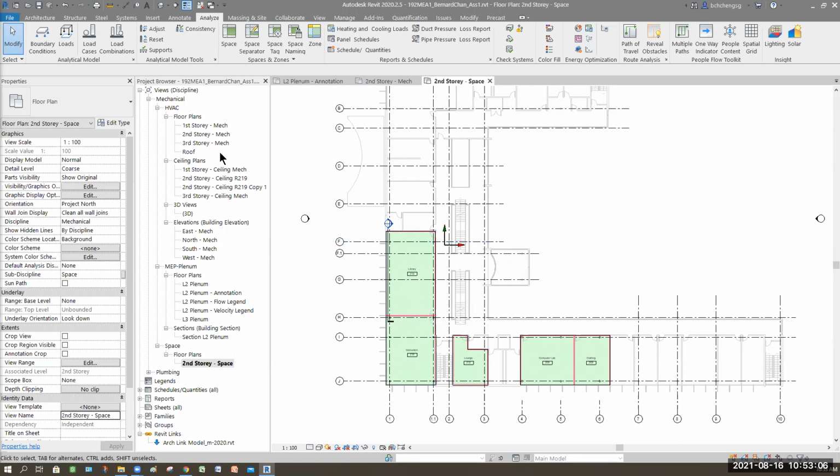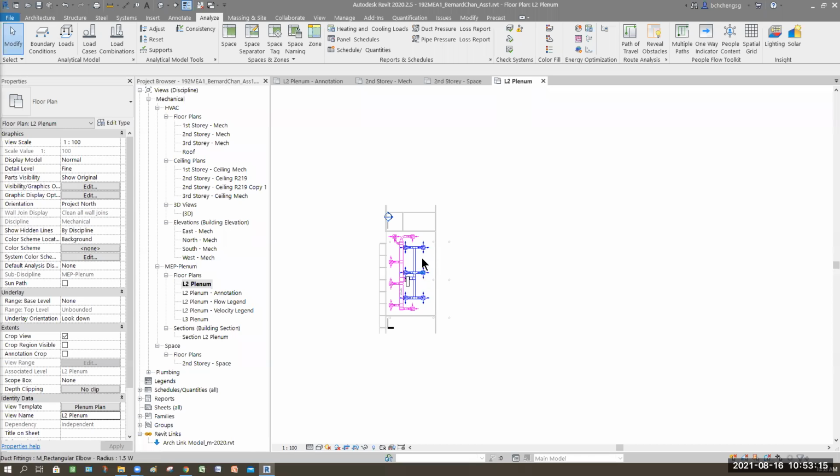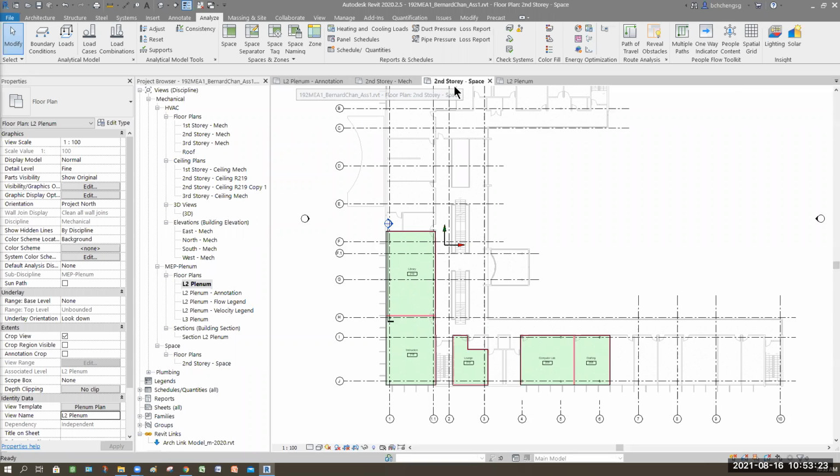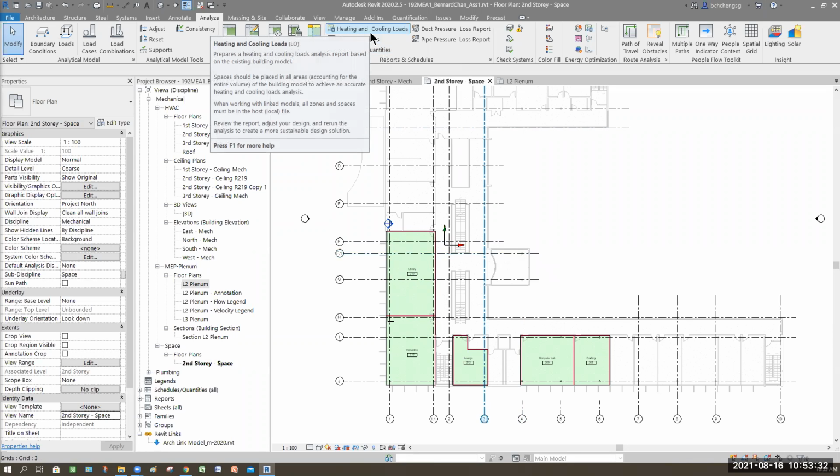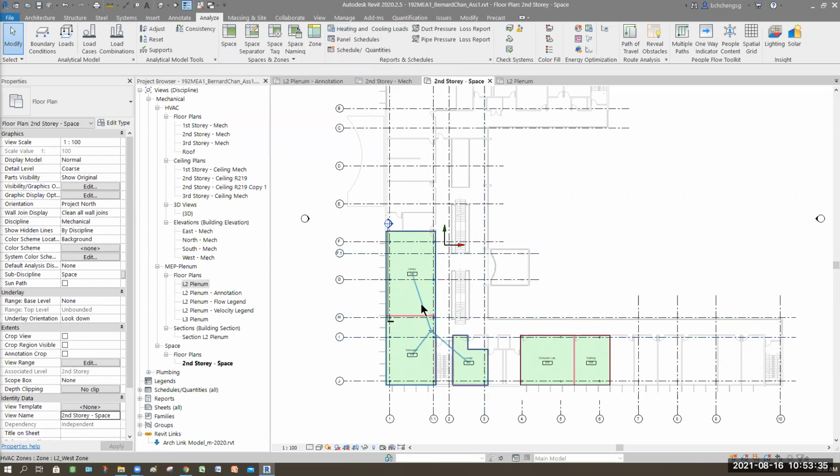So from there, you can actually determine, for our so-called planner, what is the cooling required. That means how many air terminals, what's the flow rate. You see? So this one detail will come later, but I just explain what I'm actually showing you guys. If you want to have a full data added, it's not straight from calculation. This is when I will say that the individual room data has been set up, the requirement. This is a library. What is the cooling rate for the library you require? And what is the cooling required for this?